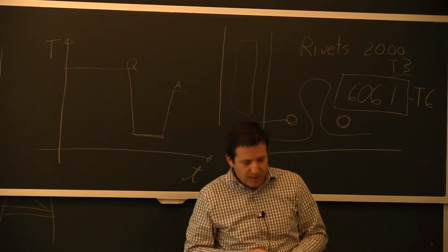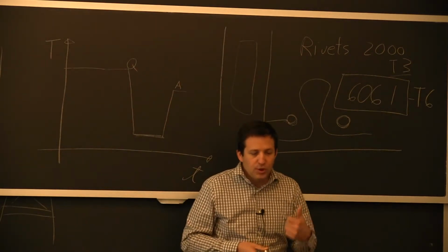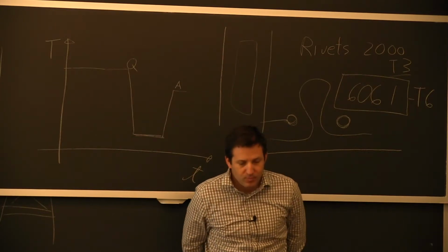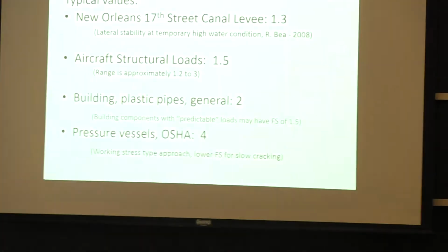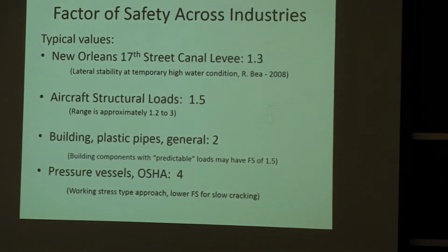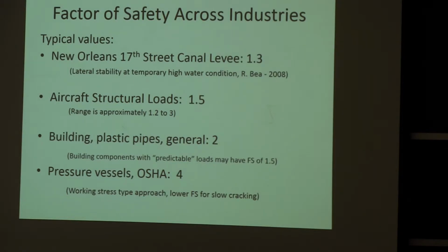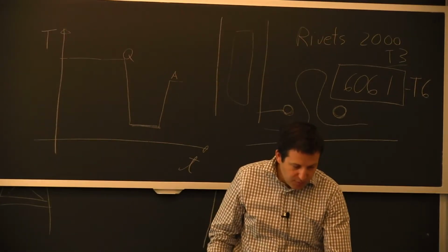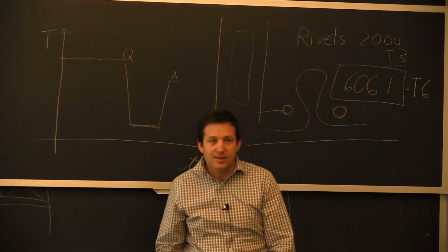So we went to the pressure vessel, the roof joist example here with a factor of safety of 2. It's more of a design based on the overall joist. So they will size so the compression cord doesn't buckle. They will size so the diagonals don't buckle. And then when it comes to the joints, there is a lot of workmanship involved to determine how good the joints are going to be. And whether you have a factor of safety of 2 on the joints, the reality is a lot of times you don't.